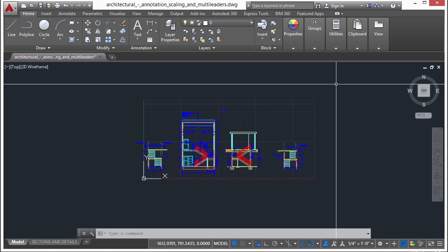to help you clean up your drawings, because a lot of times when we first start off, we do duplicate our line work accidentally, inadvertently, just because we're not used to working with it. So if you find you're snapping to something that doesn't look like it's there, but yet it's there, try the delete duplicate function, and maybe it'll help clean things up a little bit.